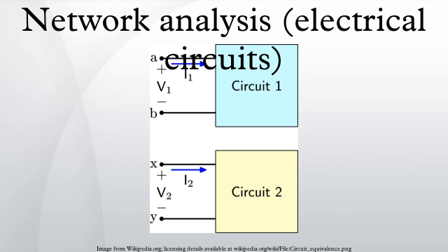Methods: Boolean analysis of switching networks. A switching device is one where the nonlinearity is utilized to produce two opposite states. CMOS devices in digital circuits, for instance, have their output connected to either the positive or the negative supply rail and are never found at anything in between except during a transient period when the device is actually switching. Here the nonlinearity is designed to be extreme, and the analyst can actually take advantage of that fact.